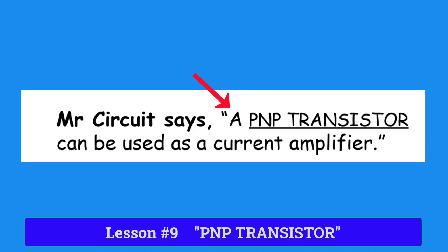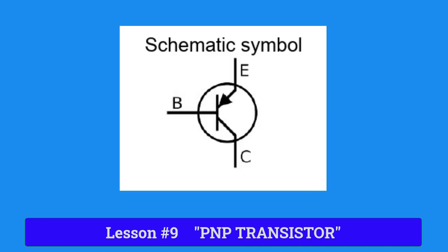At the middle of the bottom of the page, you will see a typical schematic symbol that is used by engineers and technicians to represent a PNP transistor. Notice that it has 3 leads coming out of a circle: E for emitter, B for base, and C for collector. The arrowhead pointing to the base means that this is a PNP transistor. Please copy this PNP transistor symbol into the box on the lower right-hand corner of the page.